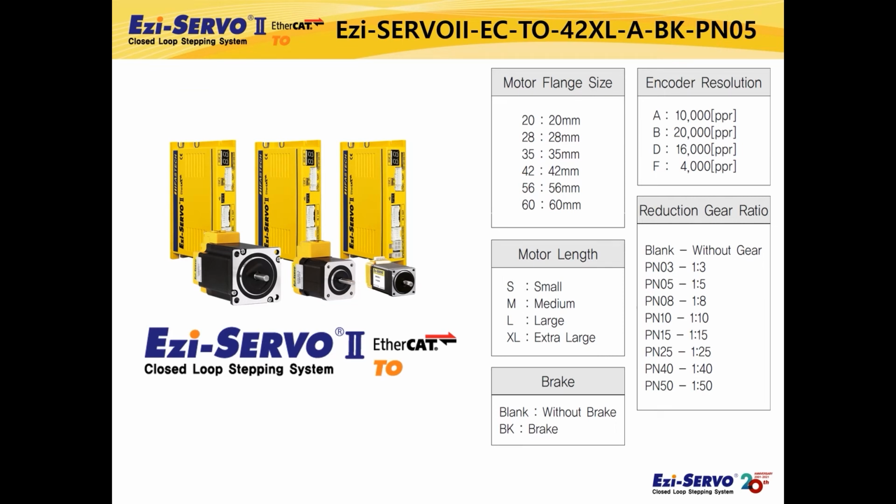You can select the motor from a NEMA 8, 20mm size motor to a NEMA 24, 60mm size motor. Motor length is the length of the motor body excluding the motor shaft, and you can select small, medium, large, and extra large length. The length you can select depends on the motor size. The encoder resolution can also be selected as shown in the table. Gearbox and brake specifications are also available.